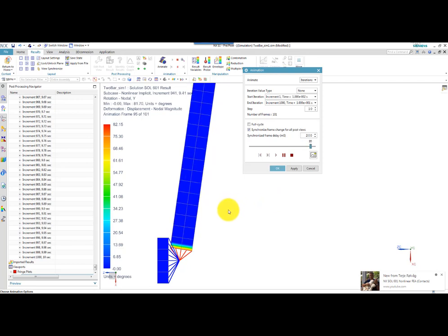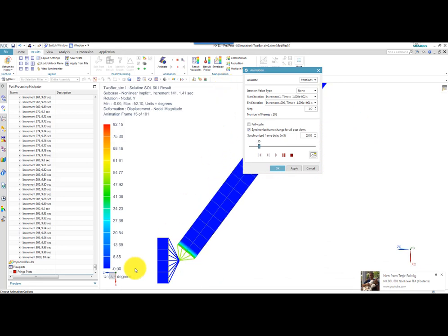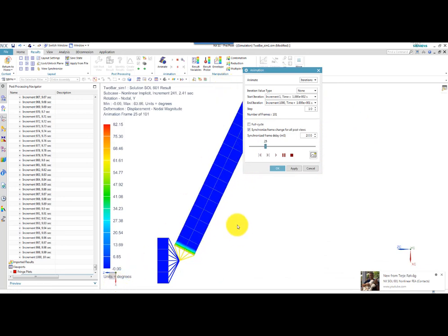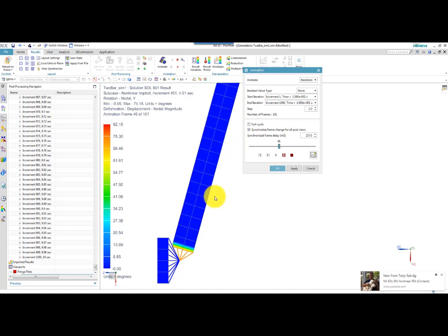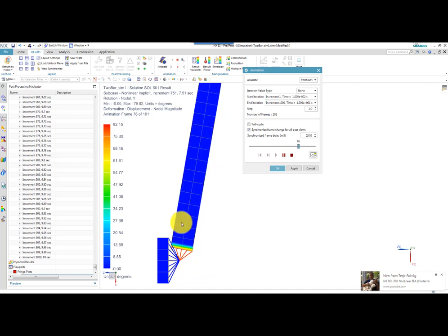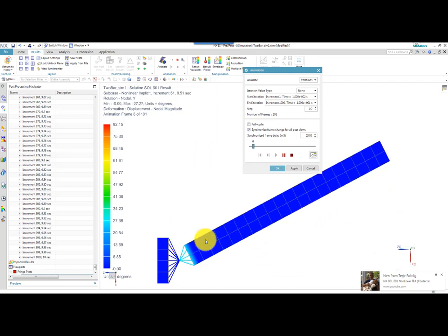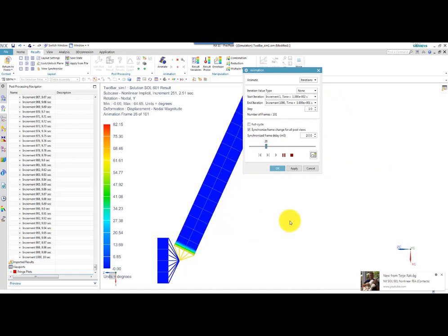And you should notice that since the load is always pointing in the vertical upward direction, that means minus x, the bar will never rotate more than 90 degrees, because the arm, which is the length of the beam, multiplied by the cosine of the angle, is going to approach 0. And that means you have no more torque adding to the system. And then the spring will stop to deflect and will stop.